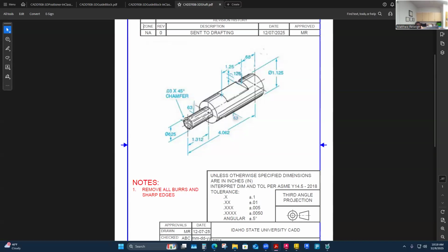So really, I'm thinking of myself being right on the center axis of this. I'm going to draw the overall length here, and then I'm going to come up half of that, essentially, because I'm at the center axis. So I'm going to draw the first line as the center axis. Then I'm going to come up pretty much half the diameter, like a radius, which is half of this. So that's 1 1/8, which is a half plus a 16th. That's 9/16. So I'm going to draw the center axis and come up 9/16.